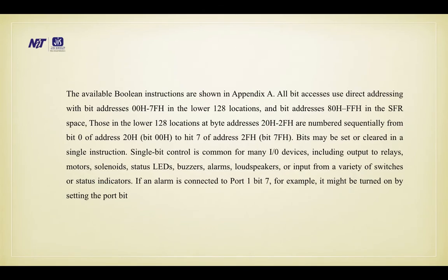The available Boolean instructions are shown in the appendix. All bit access uses direct addressing with bit address from 00 to 7FH in the lower 128 locations. So the example is given below.